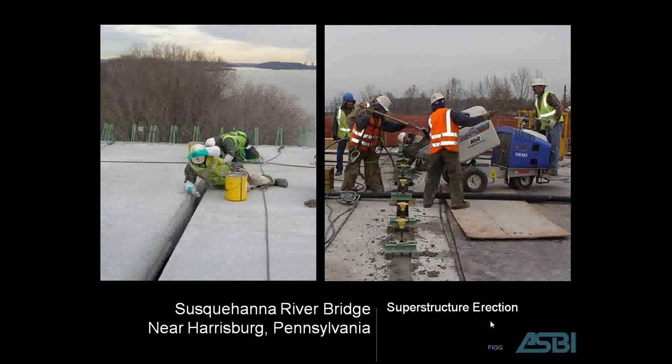Here we can see the application of the epoxy. The segments are gapped open. The workers apply the epoxy to the faces of the segments, and then, like I say, there's some temporary post-tensioning, which you'll see a detail of in a few minutes, that allows the squeeze out of the epoxy. And then at each end of the span, there's a narrow closure joint that's made. This is on the right here. You see the workers placing the closure joints.